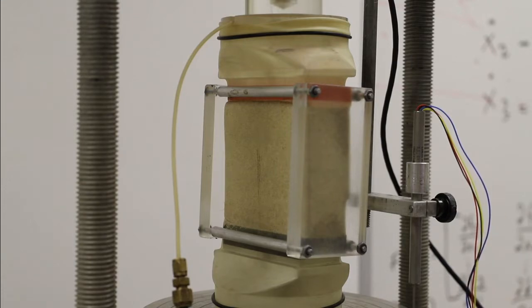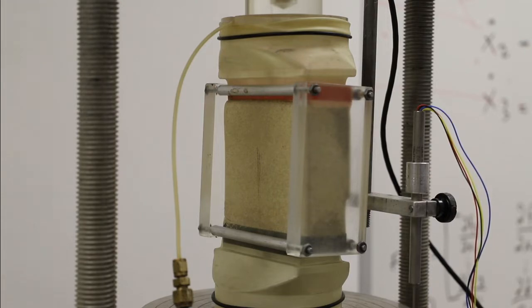So as you're processing the data, what's that going to look like, do you think? You're going to have a ductile failure or a brittle failure with a sharp peak and a drop in shear stress. We'll see when you process the data. And we'll compare between the different combinations of high and low density and triaxial and plane strain, how those different factors affect the modes that you get.